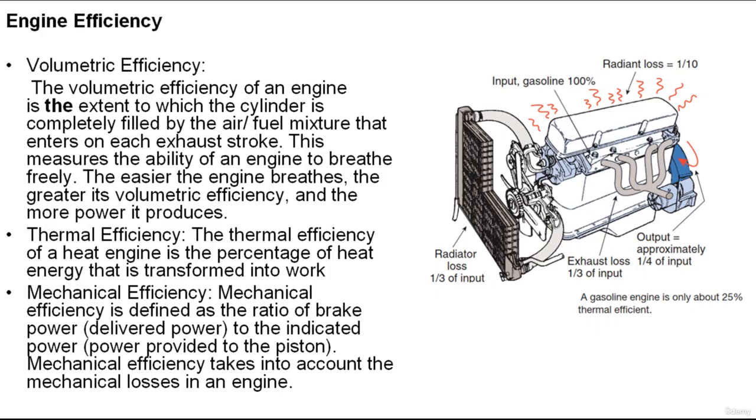Also, we'll discuss right now the engine efficiency. We have different factors to measure the engine efficiency. Let's start with the volumetric efficiency. Volumetric efficiency describes the engine's ability to have its cylinders filled with air-fuel mixture, and if the engine cylinders are able to be completely filled with air-fuel mixture during the intake stroke, the engine has a volumetric efficiency of 100%.